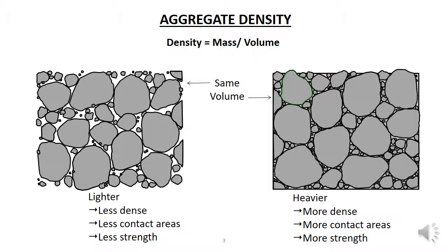Therefore, if the soil is too dry, it needs to be wetted to the required moisture content that will allow it to be properly compacted. However, too much water results in the water holding the aggregate particles apart when they are compacted, and so not being able to settle into a compact soil mass. In this case, the aggregate is too wet, and so it needs to be dried.